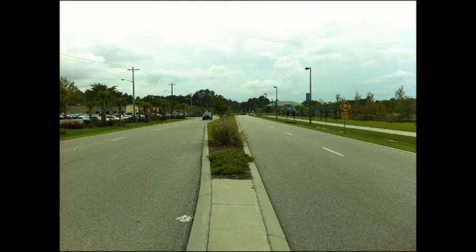As you can see, the road has a slope allowing stormwater to drain off the edge of the road and into the swales. Each section of the road is 24 foot wide with 12 foot traffic lanes, and swales are around 15 feet off of the edge of the pavement. Also, as you can see, the picture looks exactly like how the detail does.